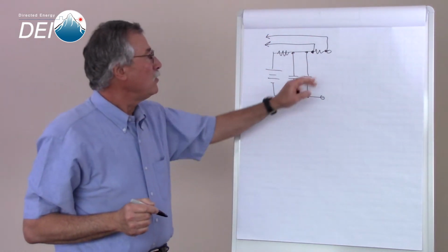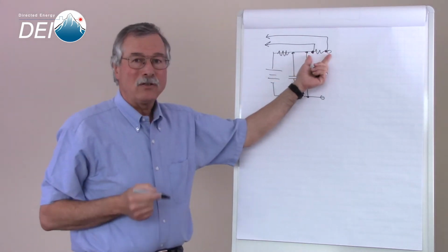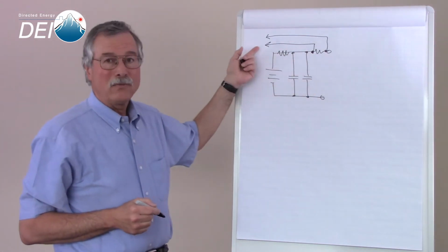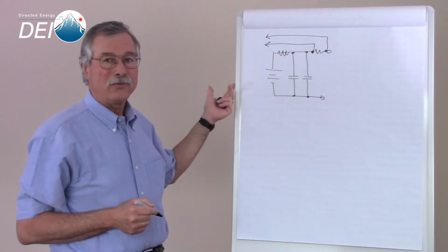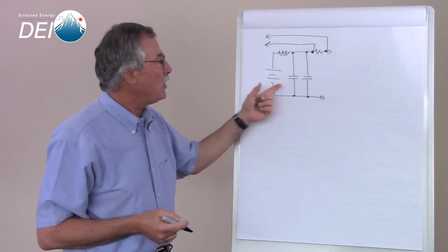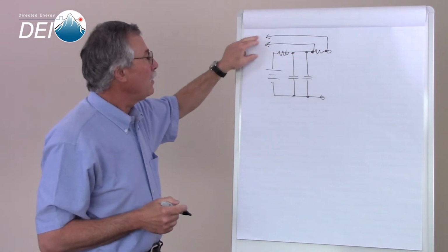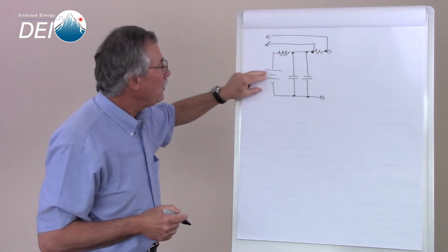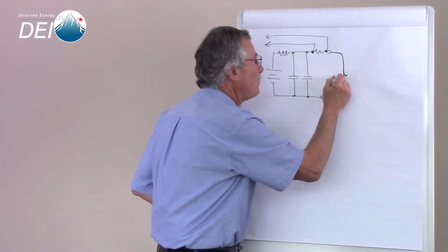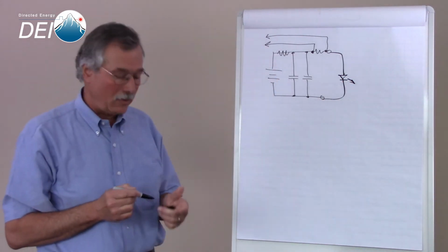What we typically do is put a small resistance in series with the output and look at the voltage being created by the current flowing through that resistor. That is feedback information which is sent to a control circuit. We create a control loop which keeps the output current constant. So this will feed some sort of control circuit which will vary the voltage so that the amount of current we have flowing through our load, here's our laser diode, stays constant.